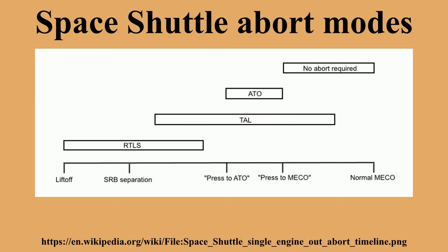Added risk due to many large pyrotechnic devices. Even if not needed, the many explosive devices needed to separate the cabin entail some risk of premature or uncommanded detonation. Cabin ejection is much more difficult, expensive and risky to retrofit on a vehicle not initially designed for it. If the shuttle was initially designed with a cabin escape system, that might have been more feasible. Cabin capsule ejection systems have a patchy success record, likely because of the complexity.